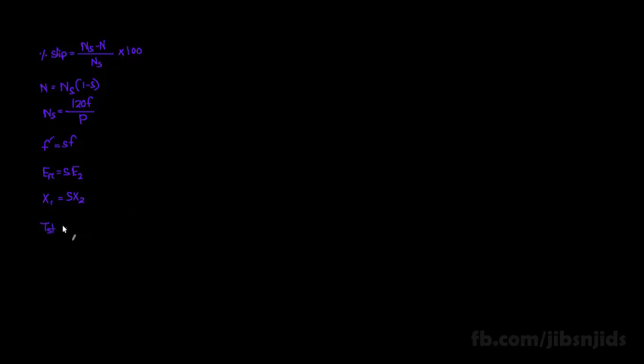We may know it, starting torque divided by maximum torque will be equal to 2A by 1 plus A square, where A is the ratio of rotor resistance and standstill reactance per phase.